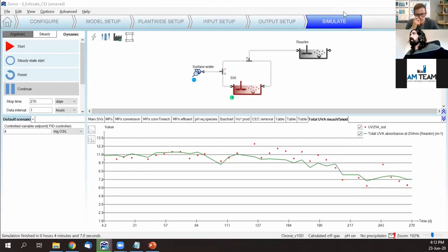Indeed, seawater we have not modeled so far. Of course, it will impact certain things. It will impact your gas transfer, and you will have to account for that. We have to tune the model if the matrix is very different, but it will also affect the kinetics. It's a matter of making the model ready for that specific water. Scavenging might be a bit higher, and salinity. It's a matter of calibrating the model for that specific seawater. It's quite a different matrix, so we expect some differences in the parameters, with regard to the scavenging especially, the ozone consumption, and the decay rates of ozone. If you look at the future usage of the model, ideally, of course, if you ask us what data you need to have a good model for our system?